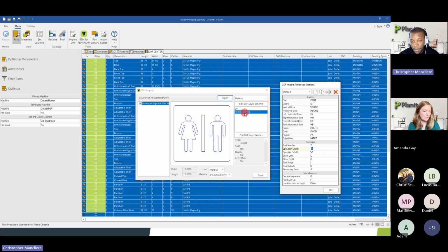When you put the depth, you put first the first digit of your size, then the decimal separator, and then the decimal number. So basically, if you have 0.225 inches, you put D0 for the digit 0, P is my decimal separator, and then 25 is the actual decimal value.